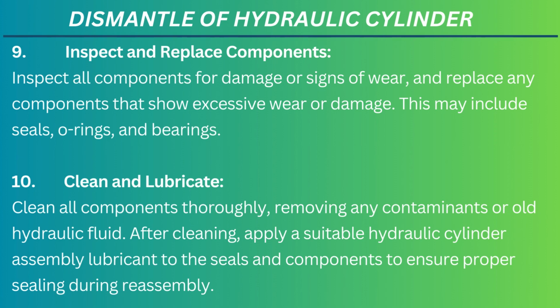10. Clean and lubricate. Clean all components thoroughly, removing any contaminants or old hydraulic fluid. After cleaning, apply a suitable hydraulic cylinder assembly lubricant to the seals and components to ensure proper sealing during reassembly.